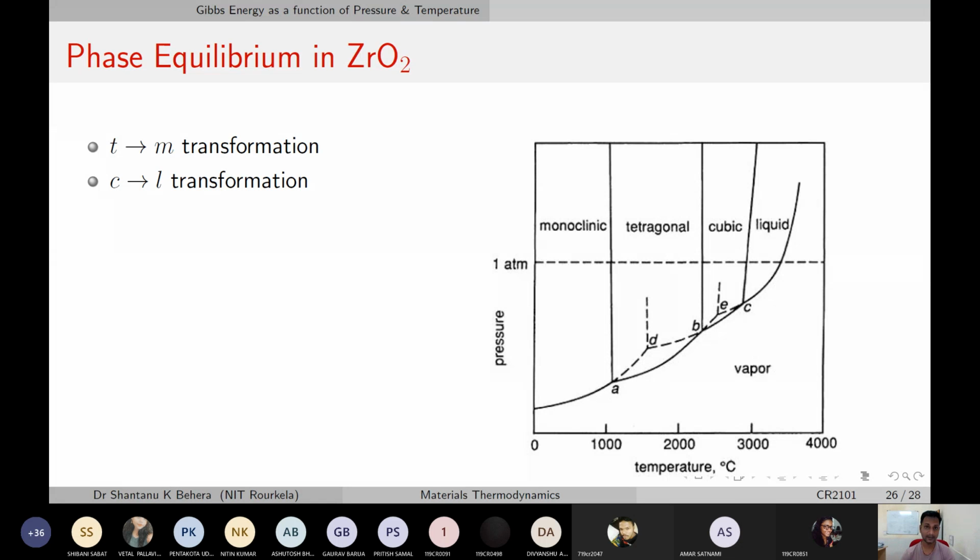Can you synthetically produce that? That's the question. The single component phase diagram is the primary one that you read, and then you will go on to read more and more important phase diagrams: two component, three component, even multi component systems. But the charm of the single component phase diagram is still there, because it helps you figure out what pressure and temperature are required so that I can make diamond films, or pressurize carbon, coal or graphite to a point that it will yield diamond.